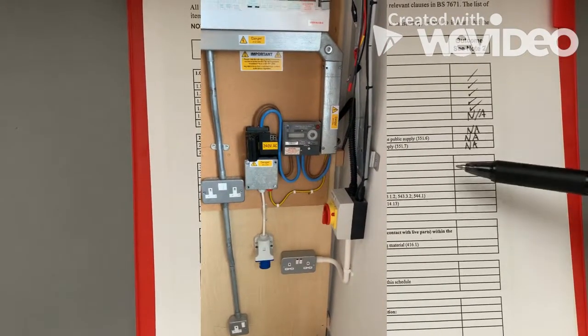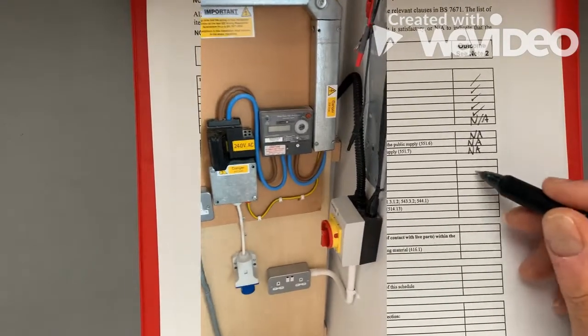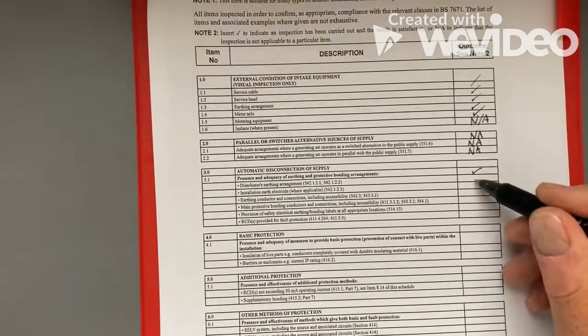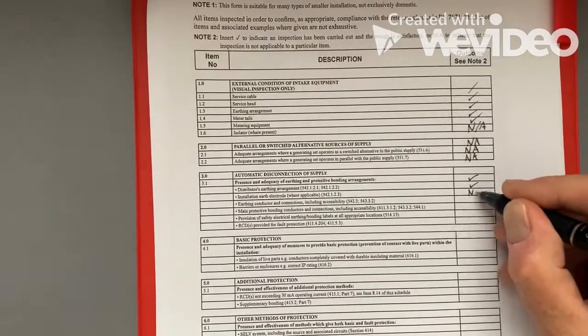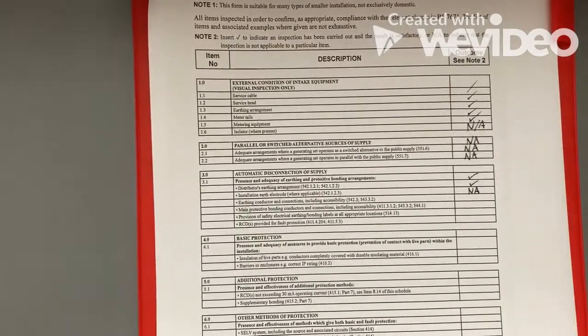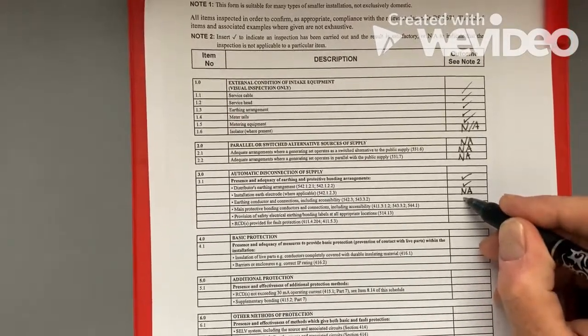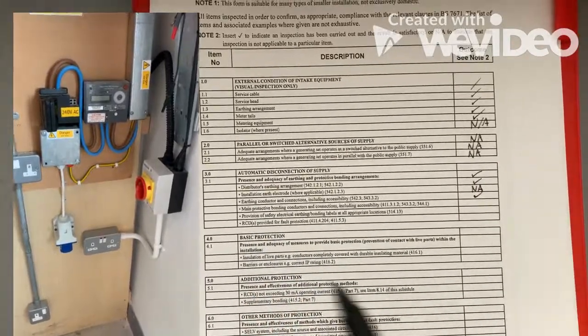So have we got presence of adequate earthing? So we can have a look at that and we can say yes. Distributors earthing arrangements, we can say that's fine. Installation of an earth electrode. Well, we've said that we haven't got one on this system, so we're going to put NA. Earthing conductor, including accessibility, we can see that. And we can see we've got that. We've got the mains protective conductor.